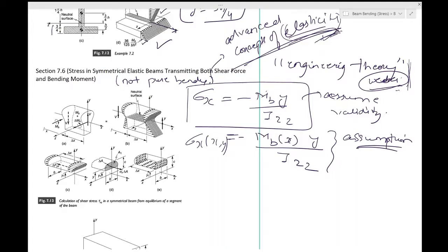Then by requiring that the equilibrium be satisfied for certain well selected free bodies, we can estimate the stress distribution which has the shear force as its resultant. Since we do not include the satisfaction of geometric compatibility and satisfaction of the stress strain relations in our analysis, we have no a priori certainty that the results are accurate. This is important.